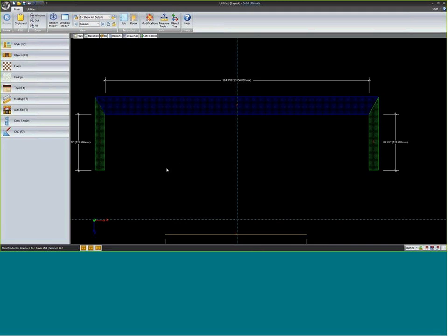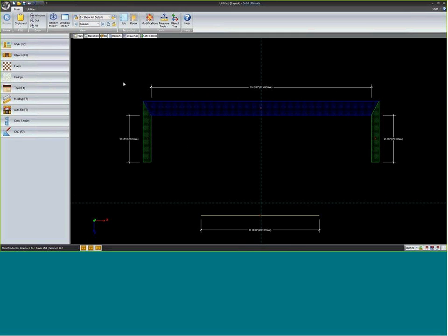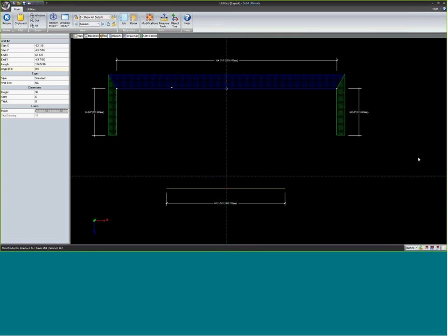You can also change the thickness of a wall at any point. You can change an individual wall if you've got a big, thick log wall or something like that you're trying to illustrate. There's all kinds of things you can do with that. Again, you can change the length or the angle of a wall. These positions up here have to do with this wall's relationship to the crosshair here in the center of your 3D camera point. I'm not going to really talk about those in depth here, but you can play around with them and see how they react.